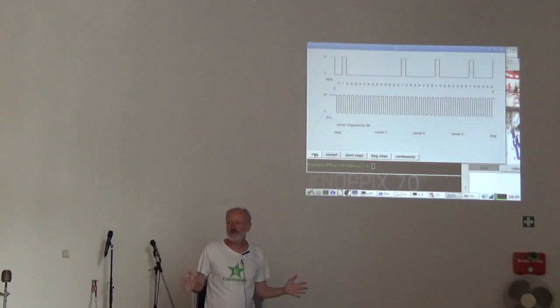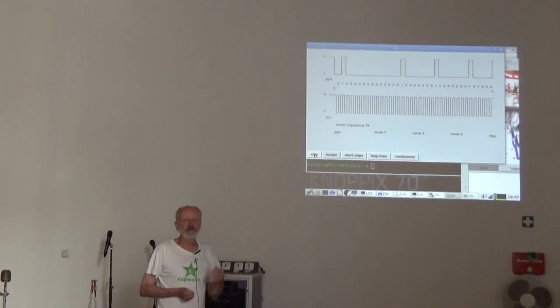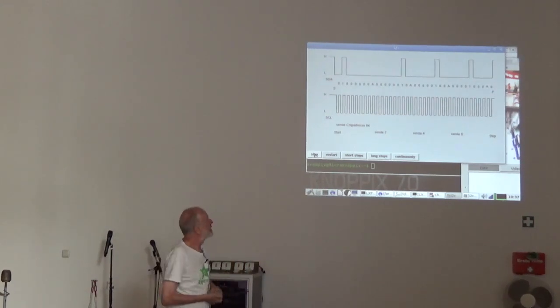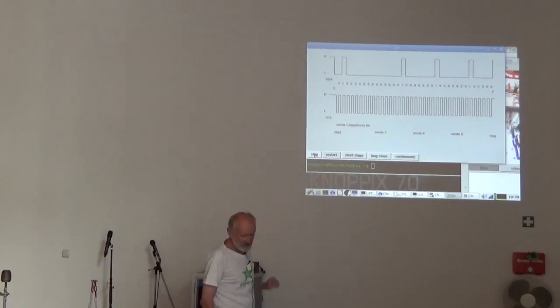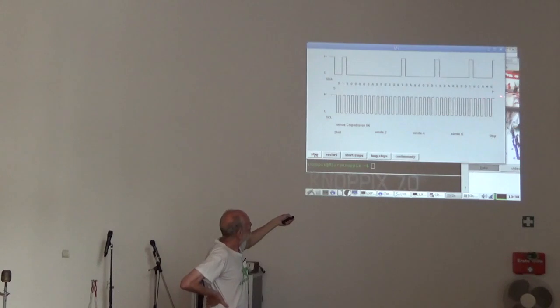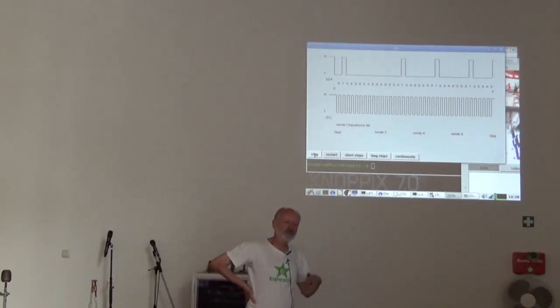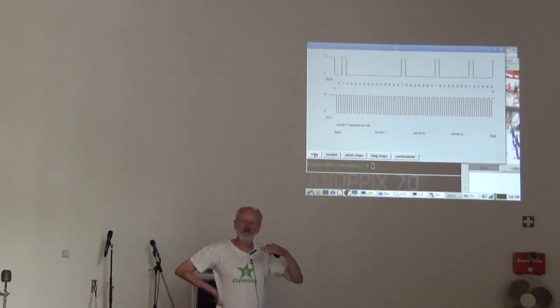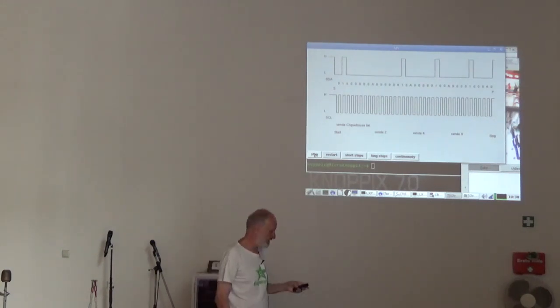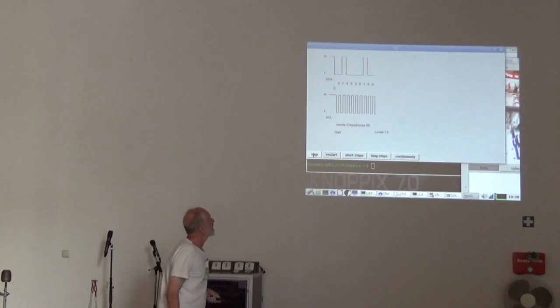When I send a sequence of data to the chip, and I want to stop it and send data to another chip, then I must do a stop procedure. And you can maybe see how the stop is. The clock is high, and then the data will go high too. This makes a stop signal, and then the bus is free for new communications. So next will be addressing another chip.